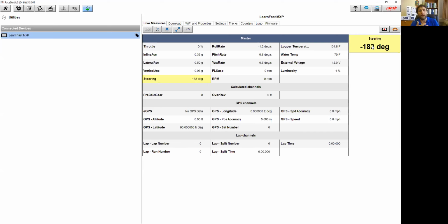One of the other interesting questions I saw in there, someone said, is it steering wheel angle or is it wheel angle? That depends what we're looking for. I always calibrate my sensor to the steering wheel angle that I hold, because when you're talking to a driver, he doesn't know where the wheels are pointed. He knows I turned this much, and we can work with this much, right?